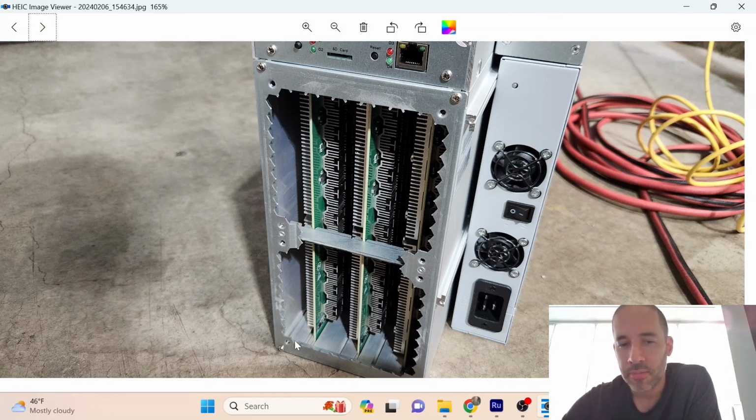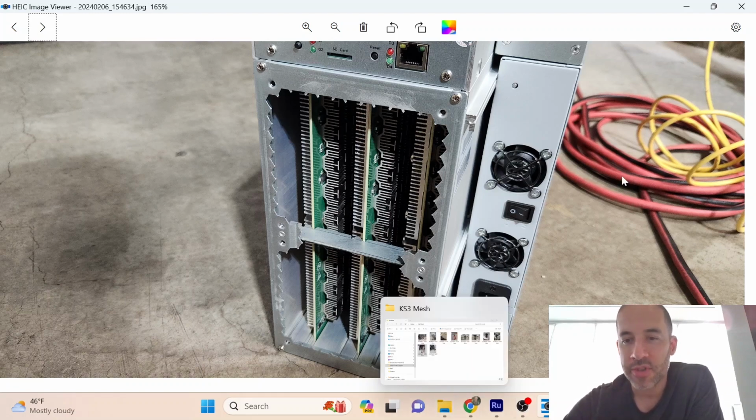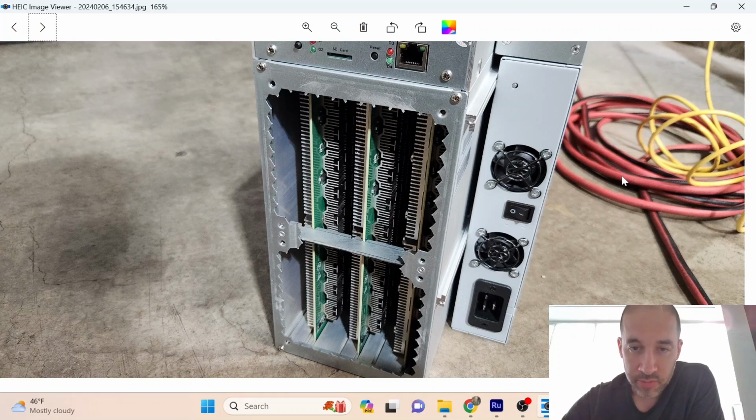But my result for this was, I actually also dropped about 3 to 4 C on each chip after doing this cutaway, and I only did it on the inlet side. I didn't really bother to do it on the outlet side, mainly because I was pressed on time. But you could perhaps get a little more flow if you cut the other side as well. So like I said, I got 12% airflow increase from just cutting out this honeycomb.